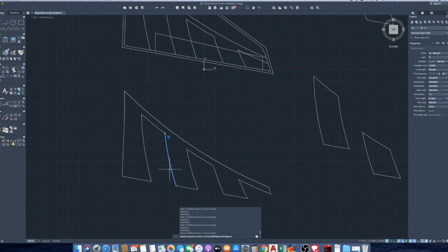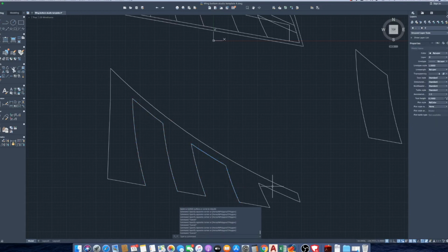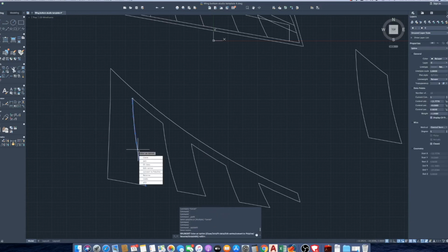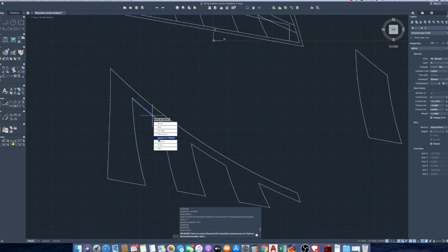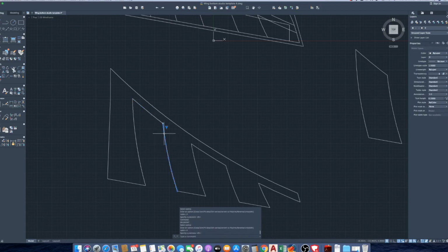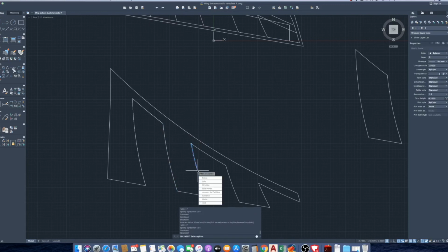So now we have a bunch of, you'll notice, splines, right? So then all these we can again convert to polyline. So we do a polyline or a spline edit command, convert to polyline, precision 25. So the same thing. We can just hit enter, select spline, convert to polyline, hit enter, select spline. Right, we do the same thing over and over again.